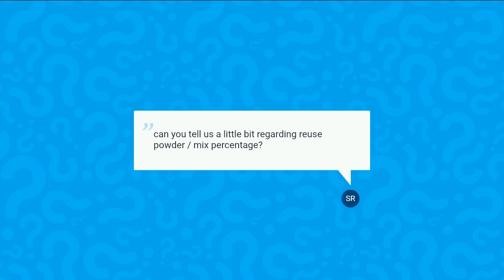So this is our print ready PA12 powder. So basically, if we have, let's say, 1 liter or 1 kilogram of the powder used for the print, you would have to add 30% of it, so 300 grams or 0.3 liter, and so on. Yes, that's right.